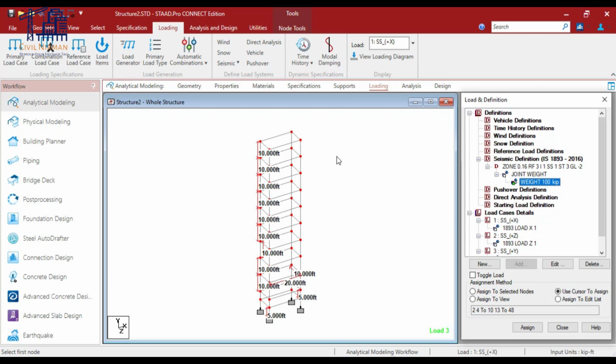So basically it covers both segments, right? The above ground portion, which is greater than minus 2 feet, and the below ground portion, below minus 2 feet. So now let's validate if STAAD splits this base shear as per code. I'll give you a brief on this.